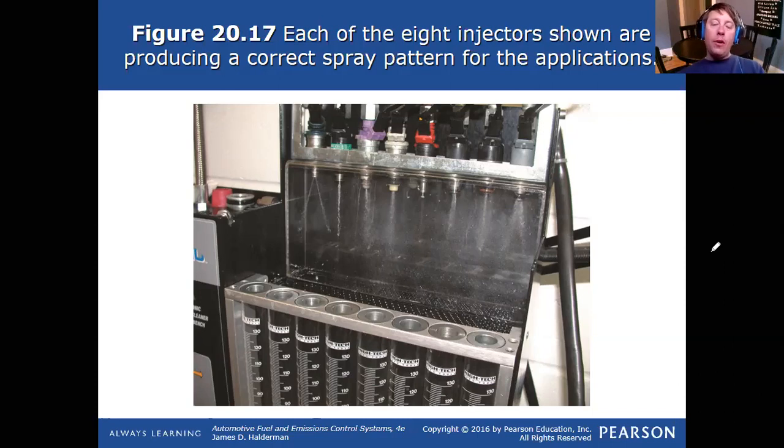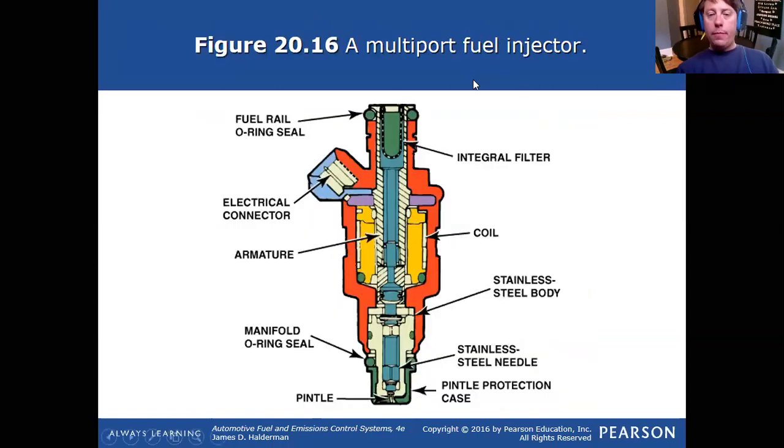Part of the injector's job is to push the fuel out in such a way that it instantaneously atomizes. And we can end up with drivability issues from fuel injectors that become clogged. If we go back to the other injector picture, the page before this, I think. Yeah, here. The pintle itself is where the fuel is leaving the injector. What will happen over time is the pintle will become carboned up.